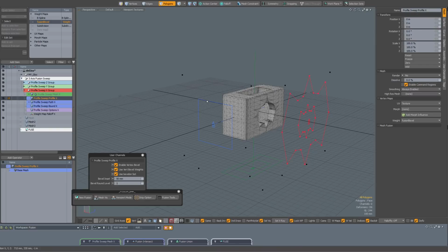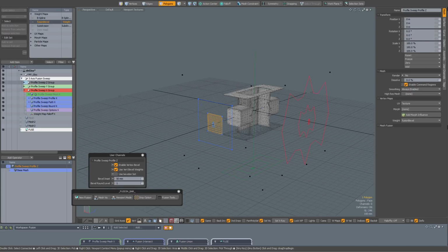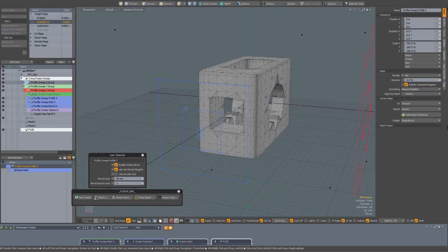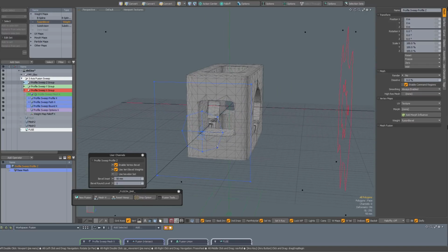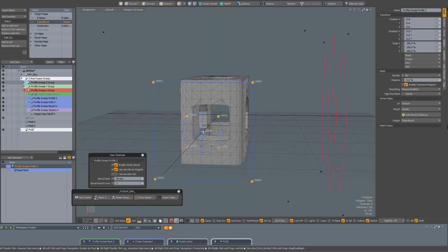Of course, for my Z profile, select the polygon, Ctrl Z, Ctrl V, R to scale, drop the tool, F to flip it, and now I have a cutout in Z, and again with that polygon selected, middle mouse button drag, press the D key, and again with my vertices do a quick select of the bevel set, and you see that those inner verts